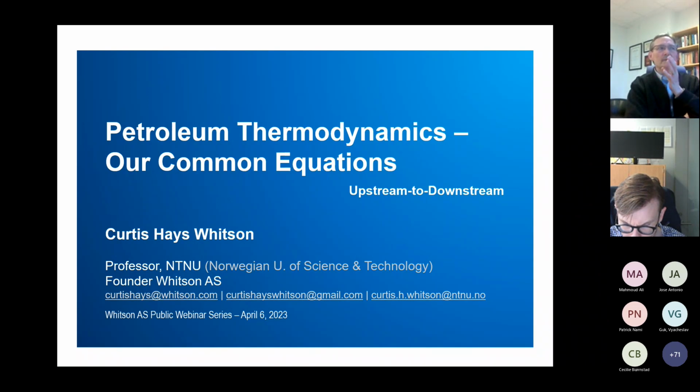CO2, I think, for a given application in general, a cubic can do a very good job, the 3-parameter cubic equation of state. And I'm sure you're always going to find exceptions, and it depends a little bit how wide the range of pressure, temperature, composition space you're looking at trying to model with a given equation of state. So for a given application. But yeah, in general, the cubic looks very promising for a lot of what's going on with the hydrogen, CO2, natural gas systems. I'm pretty optimistic.